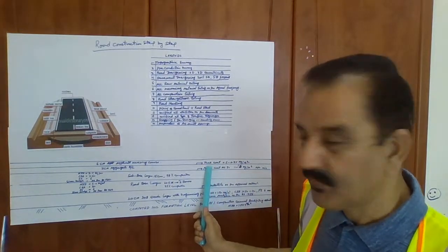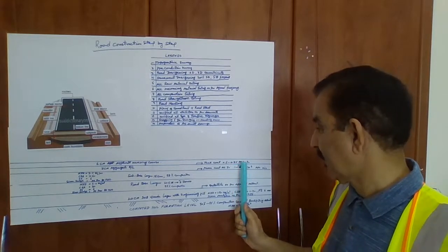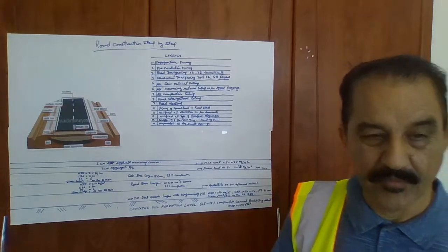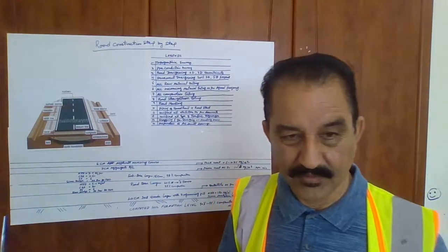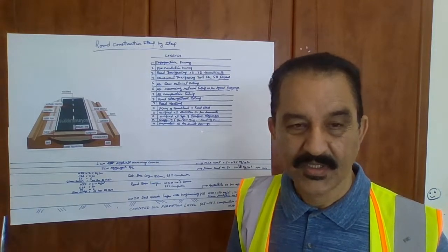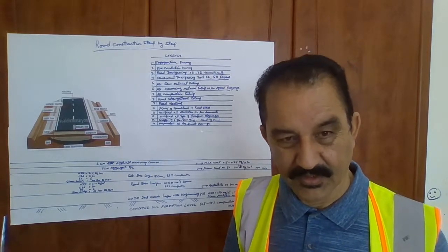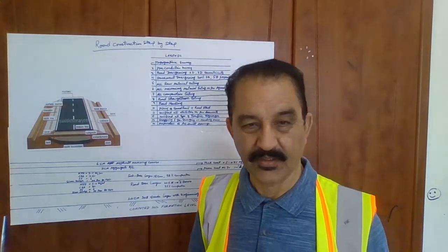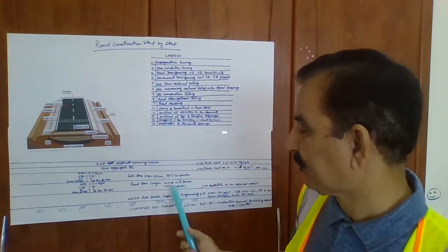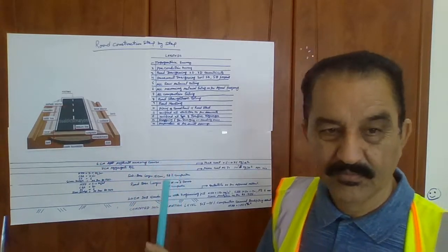The approved mix design summary for the base course should be followed. Then the tack coat application, it is 0.5 to 0.75 kg per meter square. Also, this is the bonding between the paving course and the base course. This also we previously discussed in technical sessions 30 to 40, the asphalt testing and mix design procedure. Then the 6 centimeter asphalt wearing course will come.